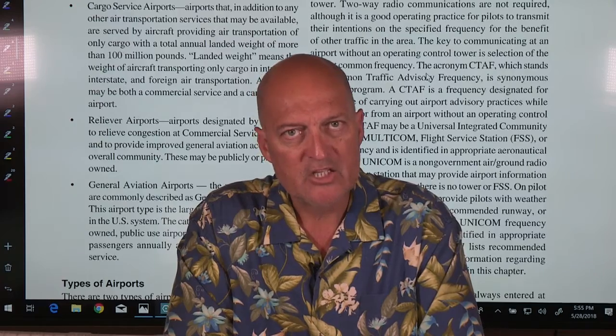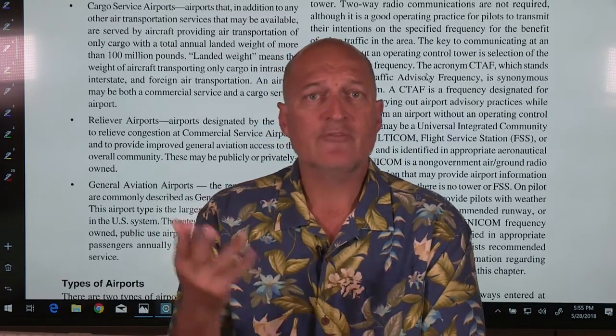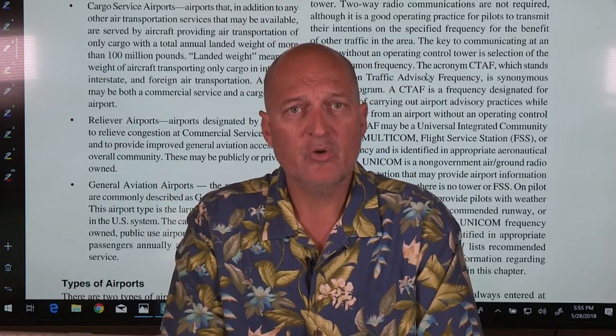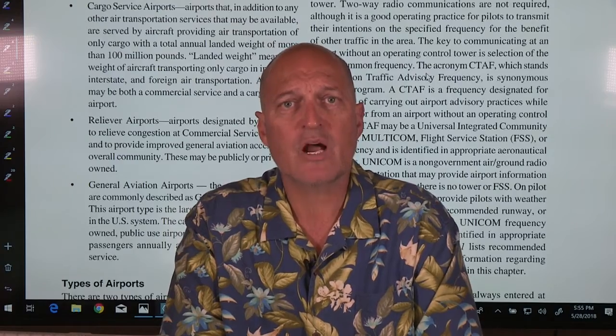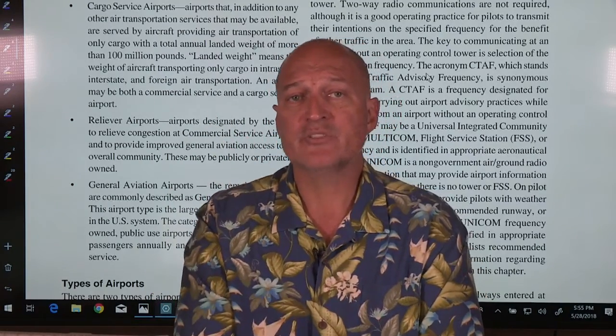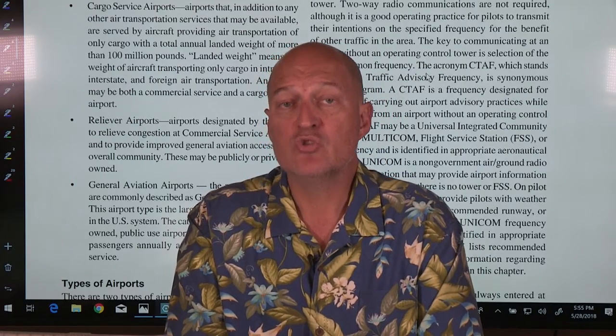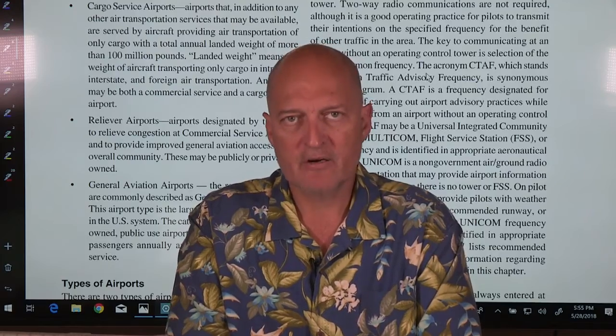Well, now what? How do you do it? It's how you begin your communications. So you'll start with, for instance, "Rifle, Garfield County. Rifle traffic, Diamond Star 141 Hotel Lima, 10 miles to the east, inbound landing runway 26, Rifle." So you say Rifle at the beginning and you say Rifle at the end. Because if there's another airport nearby using that same radio frequency, you don't want to be confusing other people or confusing people there at Rifle.